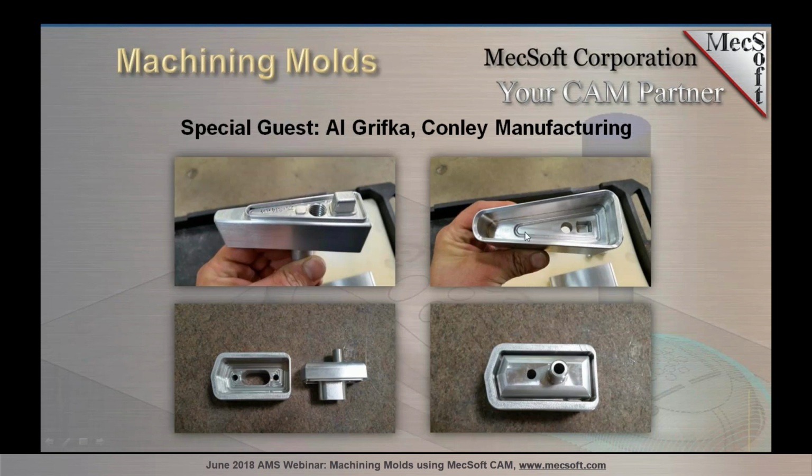and then they'll use an injecting process to actually inject. This, I believe, is for a rubber injection. So they'll inject in there to form the part, all the walls, all this contour on top and on the bottom. So this part here would actually flip right over, fit right inside there. The vacuum grooves and everything would sit right inside there, and it would locate off of this datum here and this datum here. Same thing with this part on the bottom.